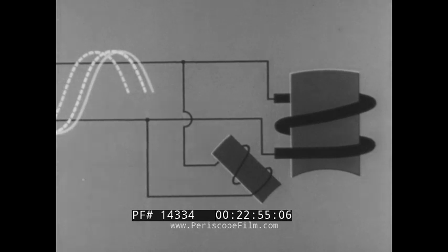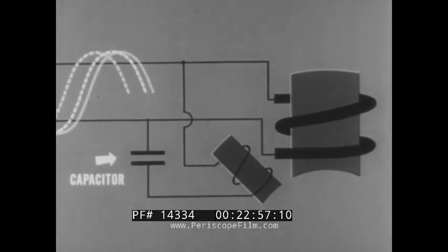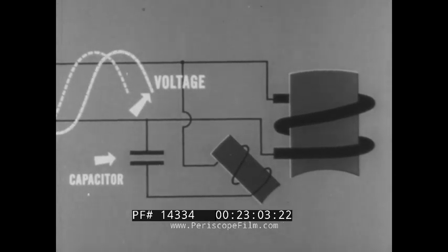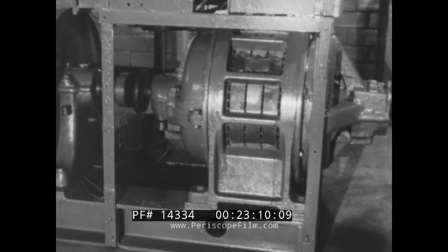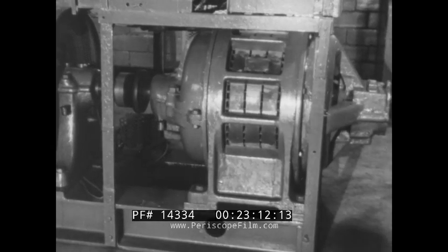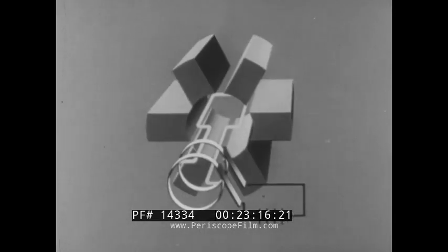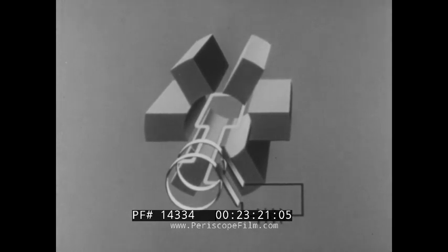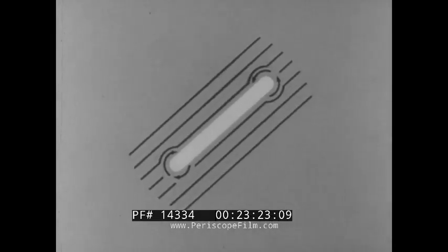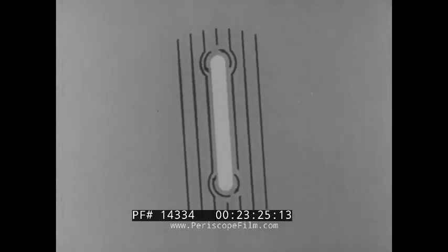In the third method, a capacitor is placed in series with the starter winding. This causes a greater phase shift between the two windings. We now have two-phase operation on single-phase voltage. In synchronous motors, there is no need for relative motion. The EMF needed for the rotor is supplied from an outside DC source. Here, the rotor and the revolving field rotate at the same speed.